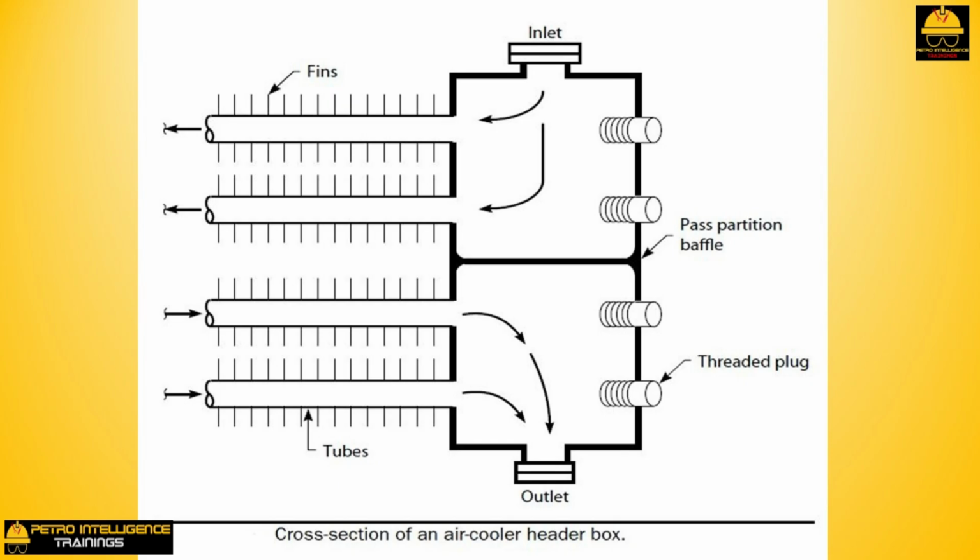This is bad. But worse yet, during a turnaround of the cooler, there is normally no way to inspect the pass partition baffle. There is no easy way to visually verify the mechanical integrity of this baffle. A few air coolers have removable inspection ports for this purpose, most do not.